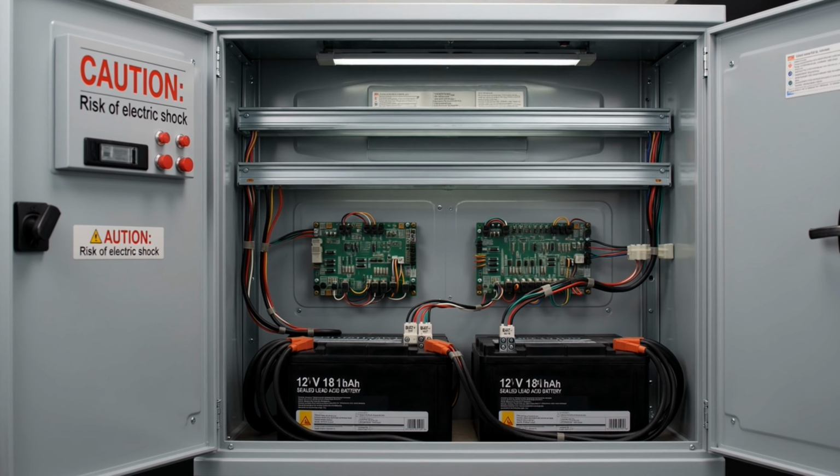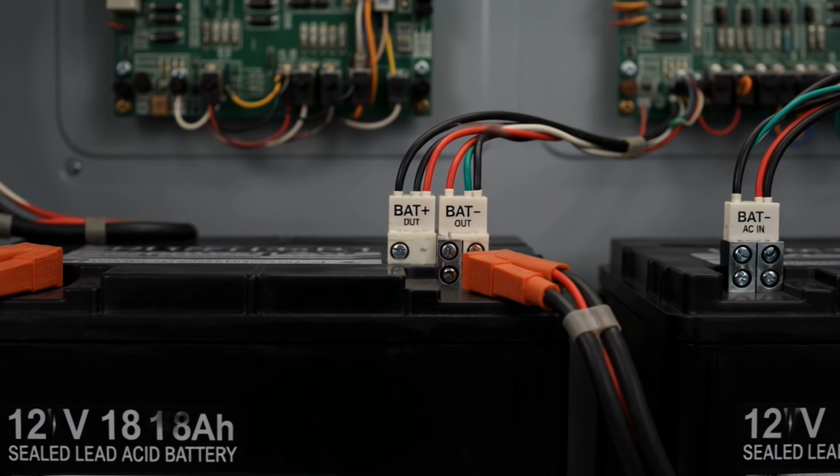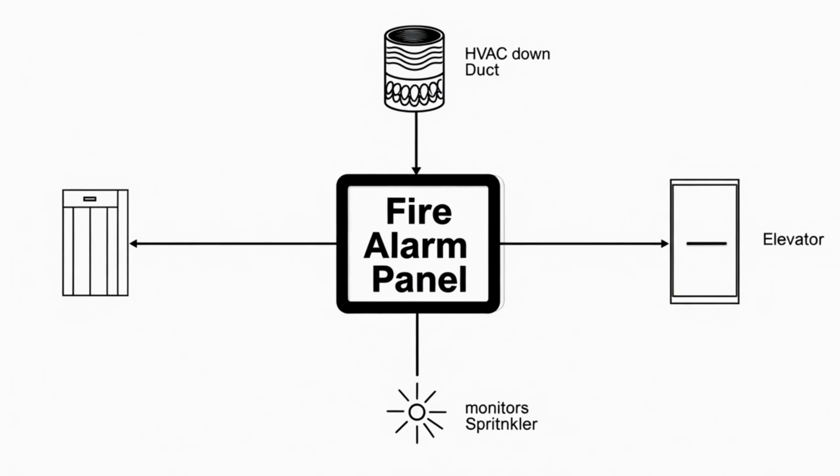Reliability is critical. Systems use a dedicated primary circuit. Backup batteries must provide 24 hours of standby plus 5 minutes in alarm. Generators offer further redundancy. A modern system doesn't work alone. It interfaces with elevators for recall, shuts down HVAC to control smoke, releases door holders, and monitors sprinkler systems.